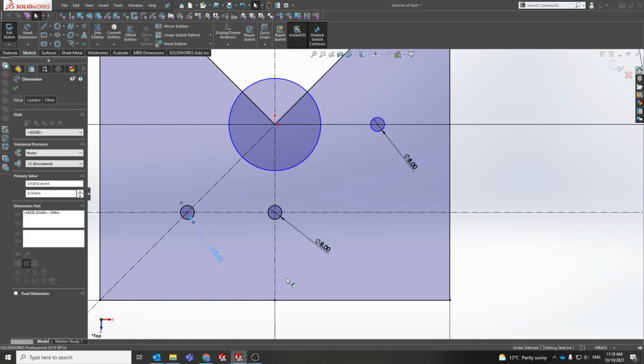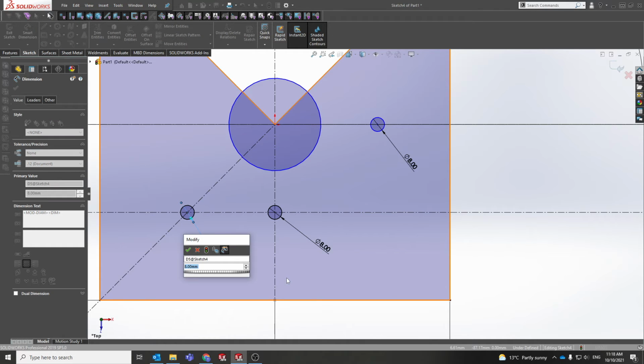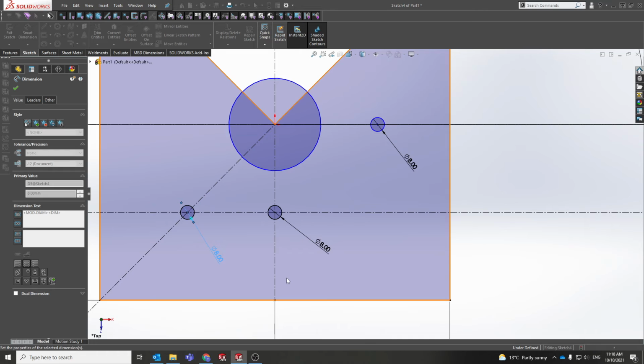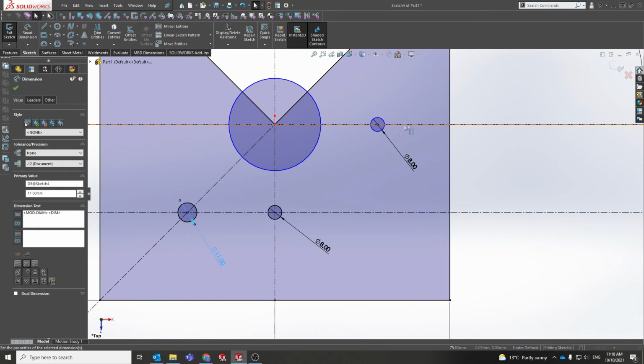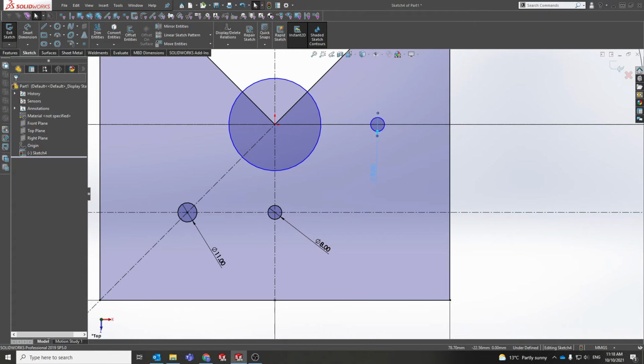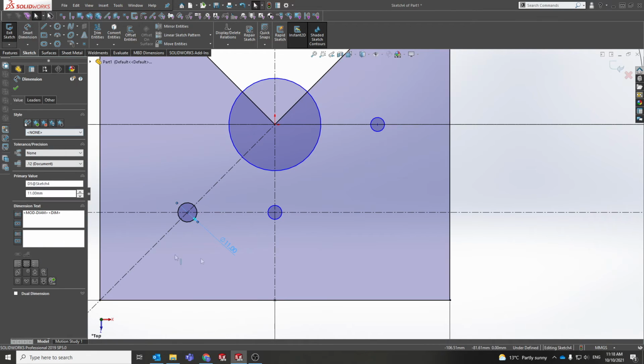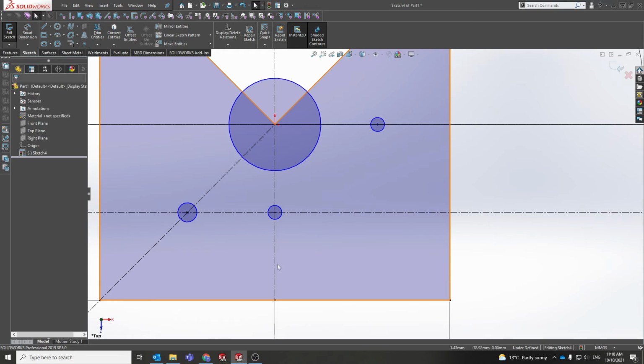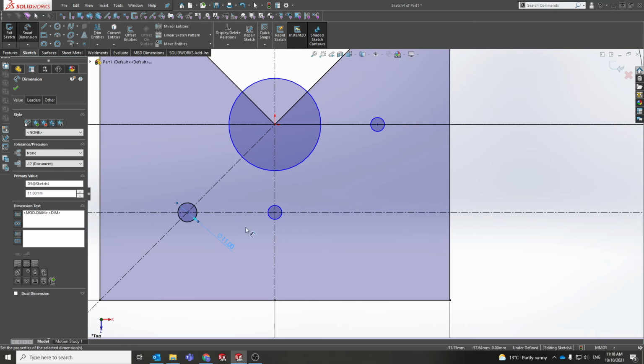I mean, you wouldn't have 8 for an M8, but you want to go, oh, let's change this to 11 now. You're going to have to go through and change them all, and this is just bad modeling, I'd say. So I'm going to delete those. As I said before, to do that, you want to drag it first, and then it will select it. It will come up with this menu here, and then you can delete by pressing the delete key on your keyboard. So coming back to this, I go, yep, 11.